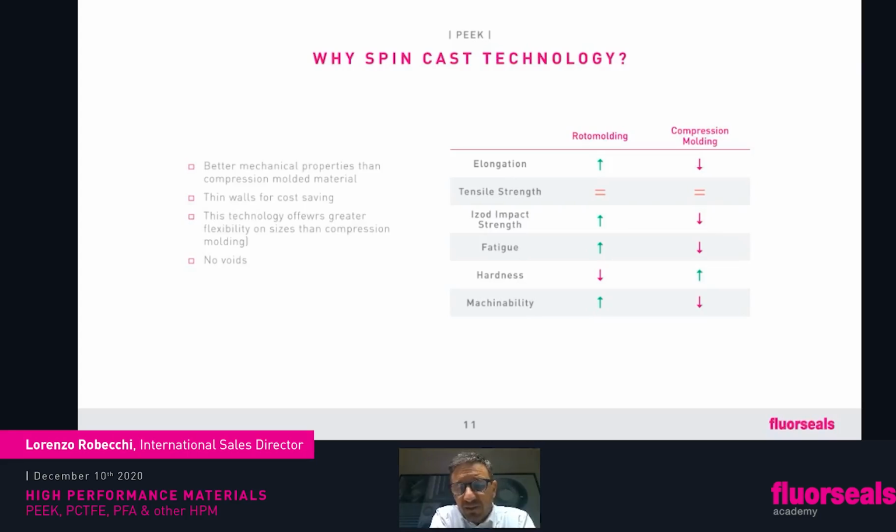You put the powder into the mold, you go up to the sintering pressure, whatever it is, above 300 degrees. And then this material goes down from 300 and whatever to room temperature. And the PEEK would like to say, well, I really would like to move here. I'm going from 300 to 20 and I'd like to move, but I can't. I'm inside the mold. What happens? It does build up a lot of tension. And this tension comes up when you machine it.